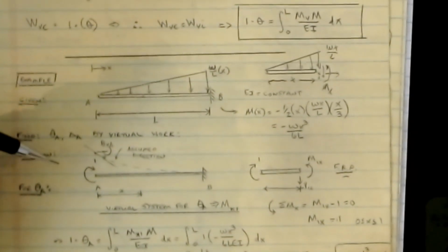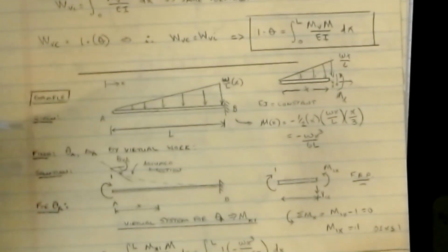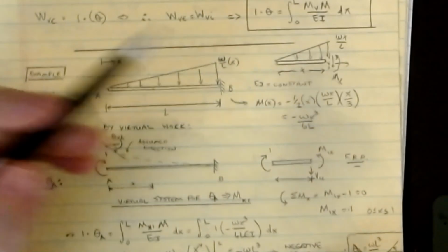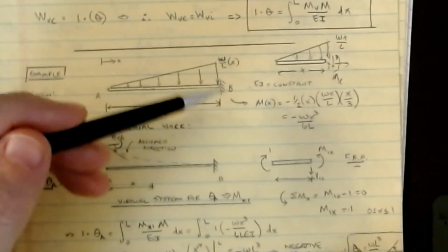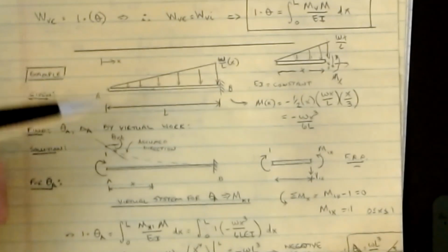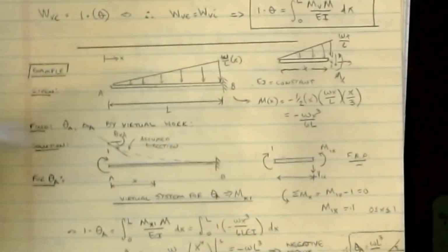Now suppose that we are after finding the displacement and the rotation at A. We're going to assume that EI is constant in this. It doesn't have to be. EI can actually vary with X. This is one thing that's cool about the virtual work calculations, is that E can vary with position, as can I, and so if I have these written as functions of X, then I just plug them into the integral and I can evaluate.